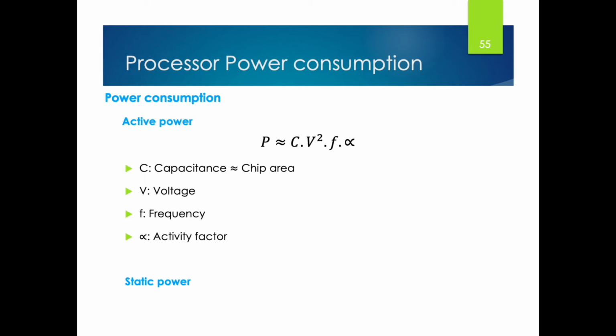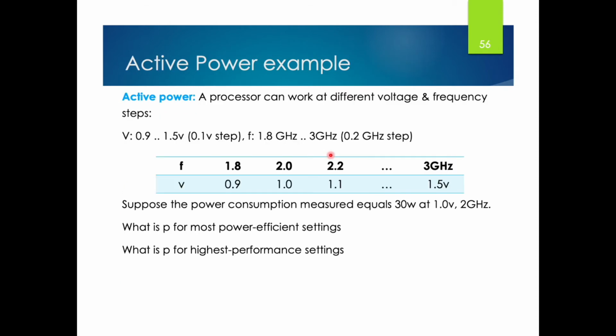The design operating frequency F is usually determined by the frequency of the clocks operating in the design. The faster the clock runs, the more it increases the switching frequency of the transistors, resulting in larger dynamic power consumption. Reducing the clock frequency to the minimal level required to meet performance will result in power saving. Now we need to calculate the active power of a processor.